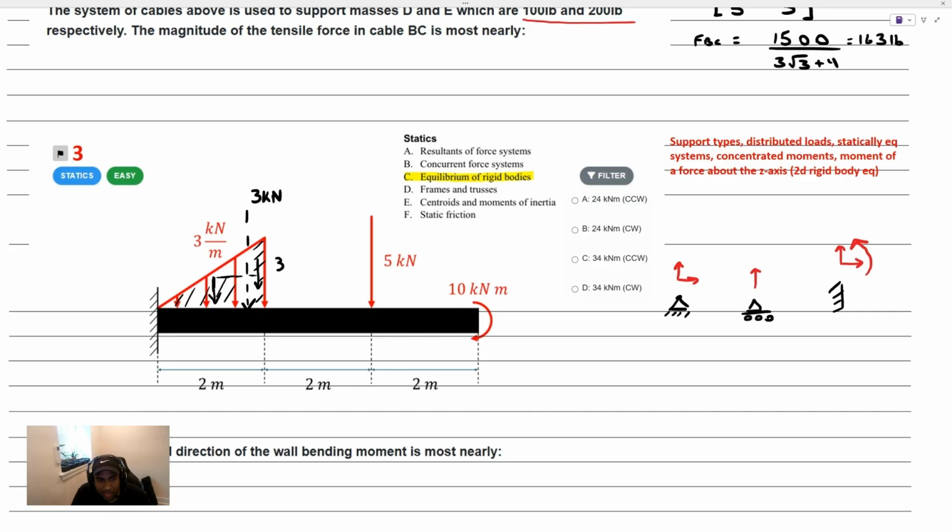So that idea of distances is how we know that we place it a third of the way from the big end, or that's how I think about it. Okay, so we know it's a third of the way. Additionally, you could check the FE reference manual. There's information about centroids, but I would recommend that you just intuitively understand that this 3 kilonewtons where it's placed on the triangle, you have the idea of a third in your mind and you place it near the big side, right? Because the small force needs more distance. So you want to place it at a larger distance away from that.